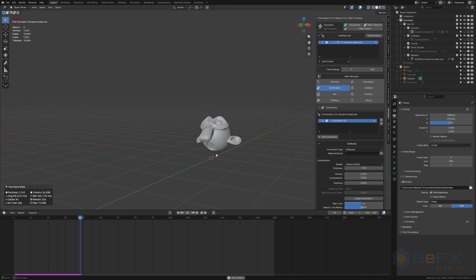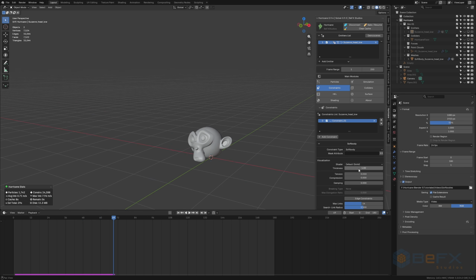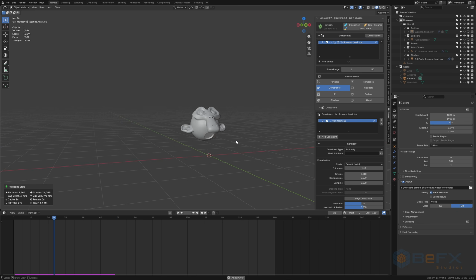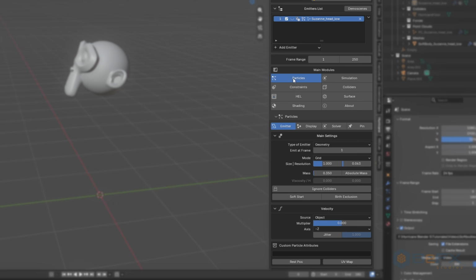With shape matching enabled, we reduce tension to 0.01. We can observe how the mesh undergoes far greater deformation upon impact, while still restoring its original geometry cleanly and flawlessly. Finally, we return to the emitter to change the emission type.